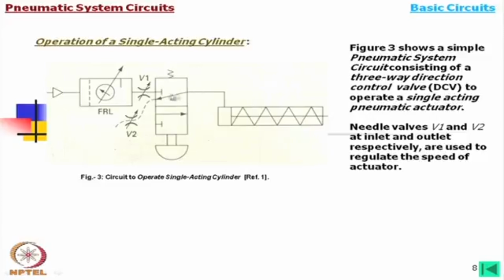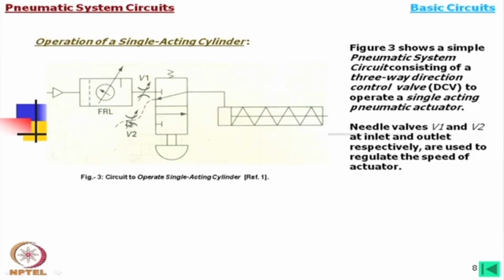Even we can also control the flow when the air is going out. Why do we need to control the flow when it is going out? So that it does not return suddenly. Say it is pushing something, but it is also being released very slowly. If there is no harm that it can return very fast, we do not need this valve at all.